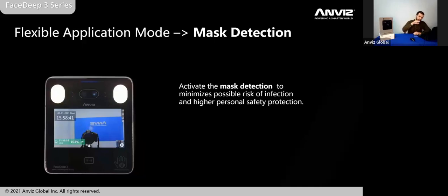You will not put the relay directly on your lock or on your motor. You will put the relay on a siren or on a red LED or on an input of your alarm central, for example, because now the relay will just trigger if it sees that someone's not wearing a mask. So two differences, in short words: access control, no mask, no open door. Relay as alarm, no mask, switch signal to the alarm central, for example.